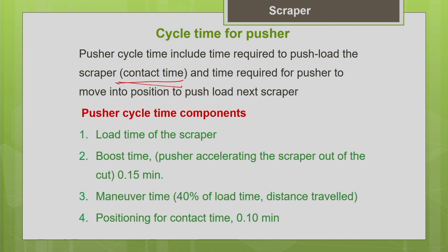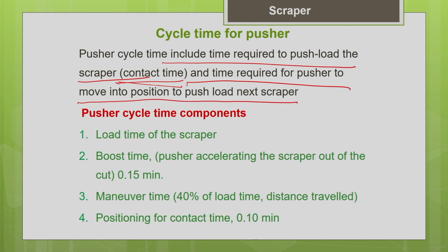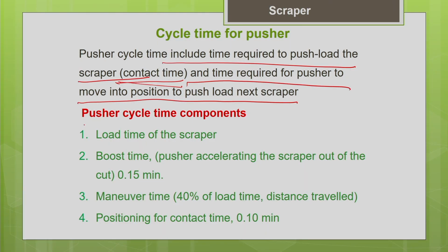Pusher cycle time includes the time required to push load the scraper. That is its contact time with the scraper during its loading phase, and apart from that, the time required for the pusher to move into position to push load the next scraper. So depending upon your site, it has to travel and spot another scraper and get ready to push it. This makes up the pusher cycle time. Let us see in detail what are all the components.